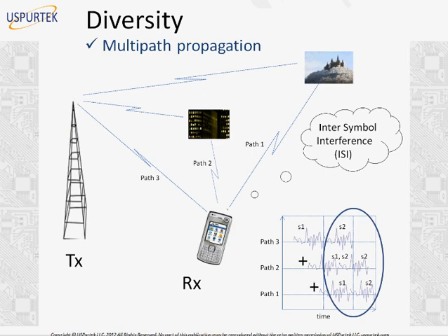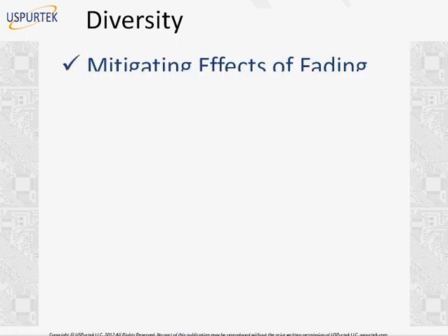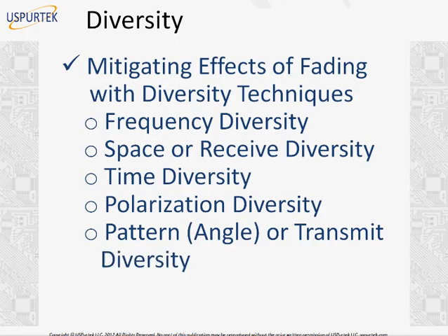So your data signals or data bits which are being transmitted using these different paths will overlap each other, and that will cause a corruption of data bits. Your data will be corrupted. And in our terms, we call it inter-symbol interference. The symbols interfere with each other. That means if you transmit some text, it might be garbled as the end result.